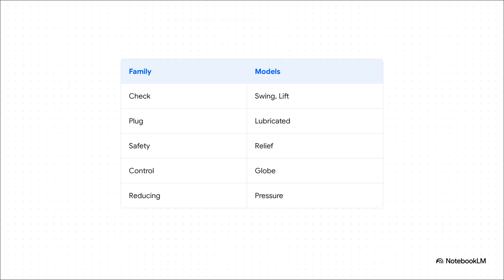Under check valves, which, remember, only let fluid flow in one direction to stop dangerous backflow, you have swing, lift, and dual plate designs. Then you've got the absolutely critical pressure relief category, featuring the classic safety valve with a lever. We even see highly specific reducing valves, engineered purely for dialing back temperature or steam. It's basically a massive arsenal designed entirely to keep your operations safe and totally predictable.